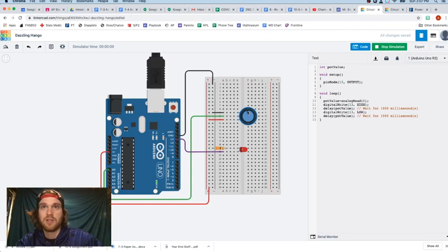So it's blinking fast here because this is down at 0. Delay is 0, which means the light's on all the time. Then you slowly open up, it's blinking fast. As I open it up more, it blinks slower and slower and slower until I get up to this top value, which is roughly on for a second, off for a second. So that's how a potentiometer works. We can sit here and drag and change the value that it is blinking. It's a pretty cool gig.